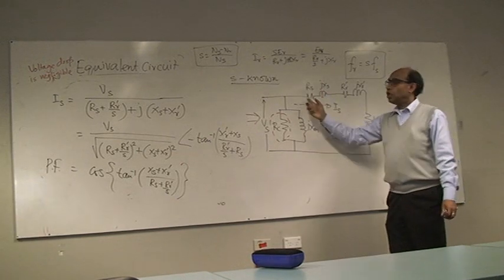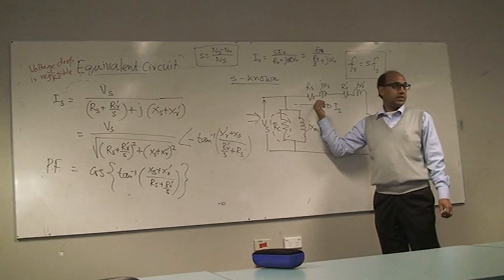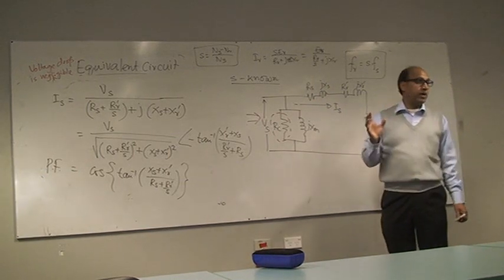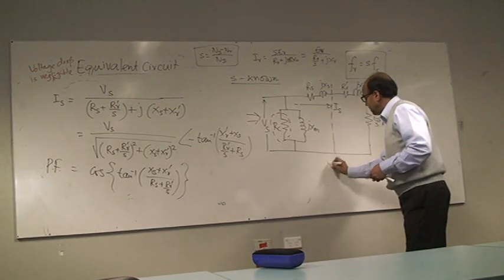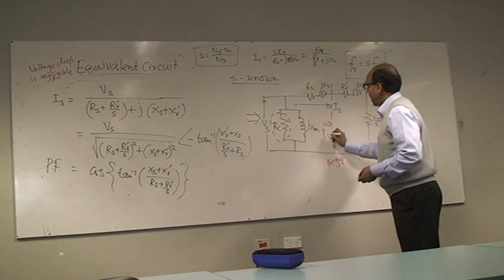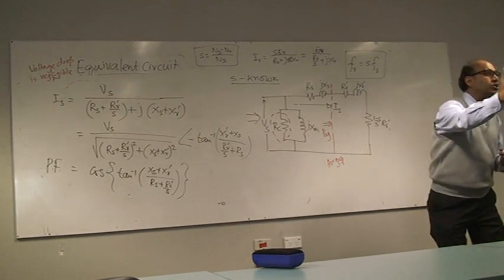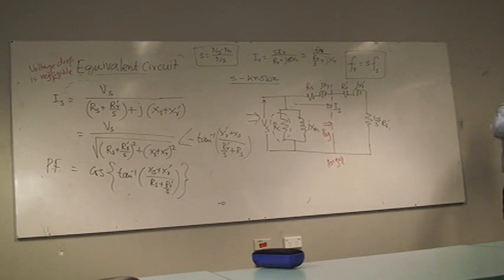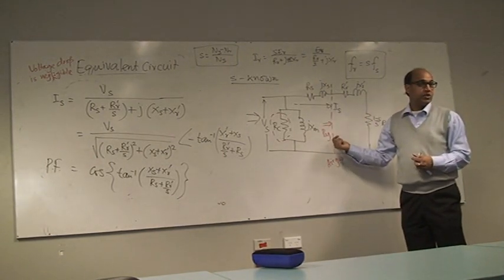Second part is the loss in the stator resistance. So stator copper loss. Once you take these two power losses from the input power, your power then goes here. So this is your air gap. We call this power the air gap power. What is the meaning of air gap power? The power which is actually crossing the air gap. It's like jumping over a drain, or a river. It's the power which is crossing from the stator to the rotor, crossing the air gap.